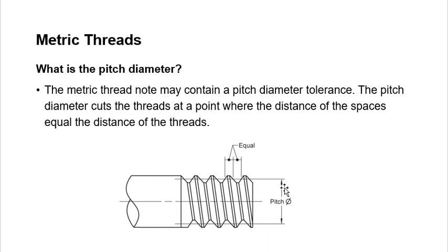When you look at it from the side view, you're going to see this surface. We know the major diameter and the minor diameter. Your pitch diameter is in between them, because we're measuring with the line between the major and minor diameter, the center line between them, and then you measure that diameter from that side to this side of the circumference.